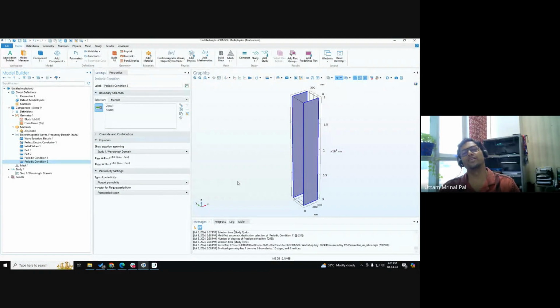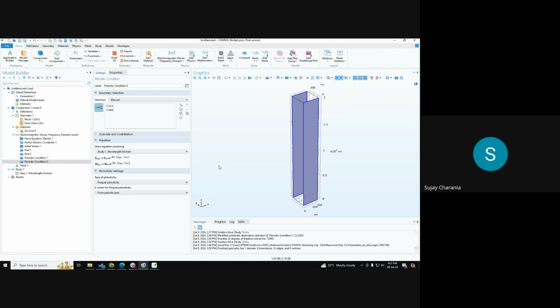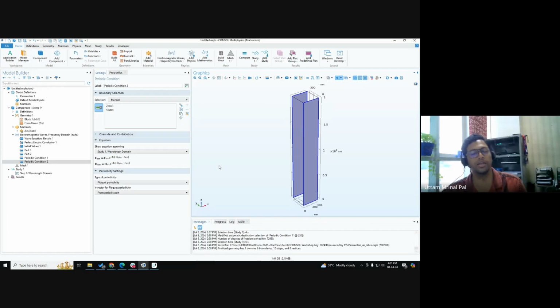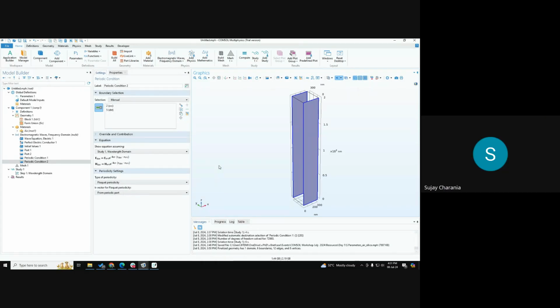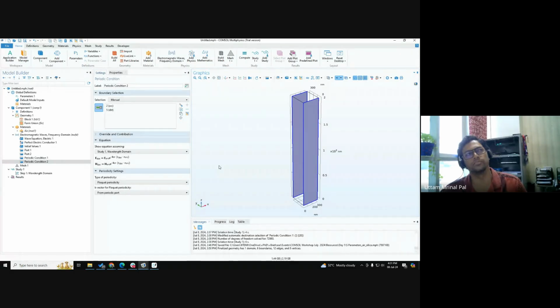No, no. So don't worry about that as air. Because this is a modeling geometry, right? We need to terminate it somewhere, and PEC and PMC are all terminating boundary conditions. One way to look at it is that a perfect electric conductor short circuits the electric field.